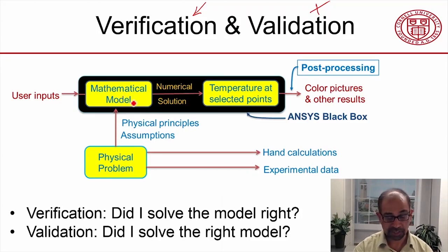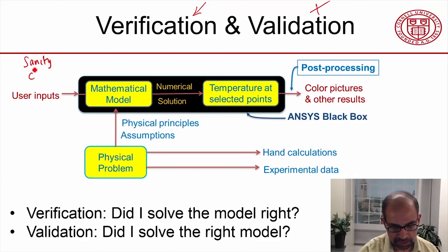Under verification, the first thing is to do sanity checks, and we have been doing that as we've gone along, looking at temperature distribution, looking at heat flux vectors, and so on.